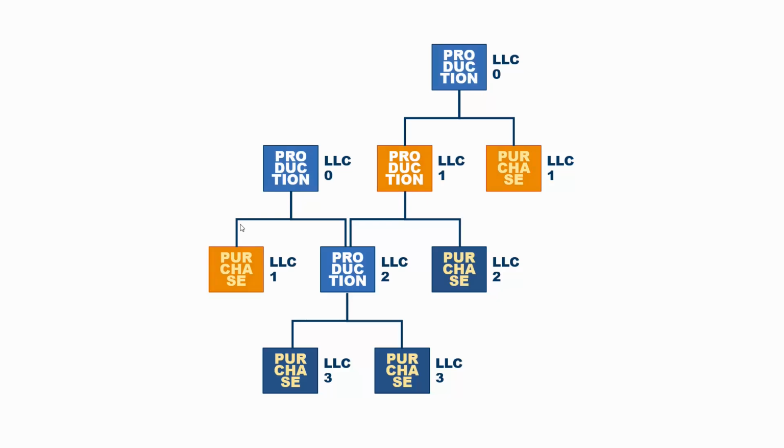item. But an item could go, if we look in the low-level 2 coding, the left-hand one of those items is on low level 2 because it goes into both a low-level 0 item and a low-level 1 item. And therefore, in the name low-level code, we have to find the lowest possible level that it goes into. In this case, it's 2 because it has on the right-hand side a low-level code 1 item. And this is the way we have to do planning.